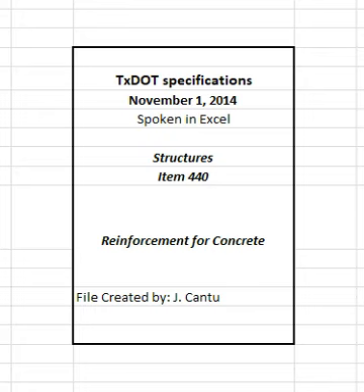3.6.2 Placing. Do not flame cut coated reinforcement. Saw or shear cut only when approved. Coat cut ends as specified in section 440.3.6.3, repairing coating. Do not weld or mechanically couple coated reinforcing steel except where specifically shown on the plans. Remove the epoxy coating at least 6 inches beyond the weld limits before welding and 2 inches beyond the limits of the coupler before assembly.